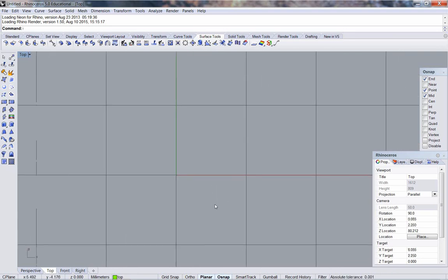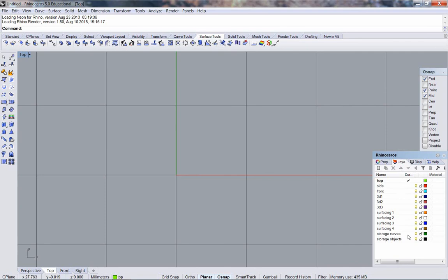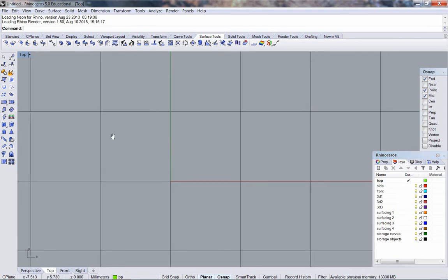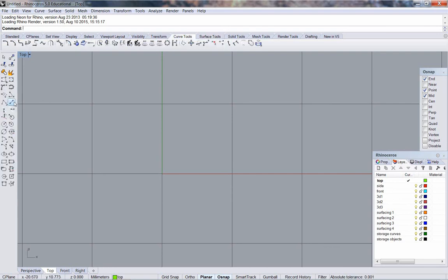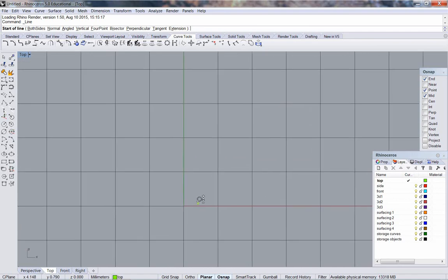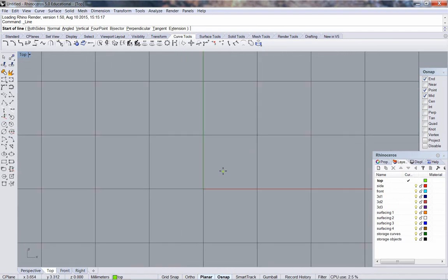Going to draft our transparent ring. It's a tapered ring band, tapering from 10 millimeters down to 4. First step in drafting is to always lay out your construction lines, which we will do based around the center of the front view.